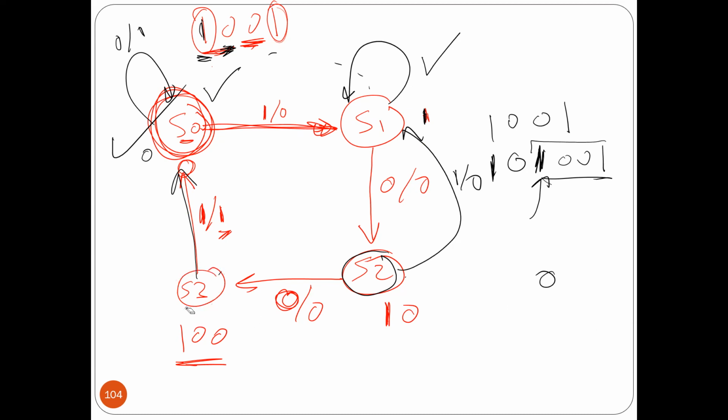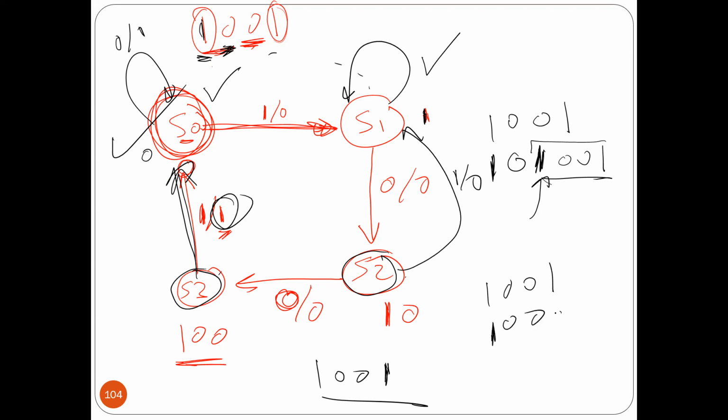Let's look at this one here. So again, I am done. Listen to me. You are done if for every state you consider 0 and 1. You consider the two cases, two possibilities. Now, if I come to here in S3, so now I have 1, 0, 0. Is that okay? And then after that, I got 1. That's why I'm going to go again to look for a new sequence, and the output has to be 1. Is that okay? What if I'm looking for 1, 0, 0, 1? I got 1, 0, 0, but after that, I got 0.